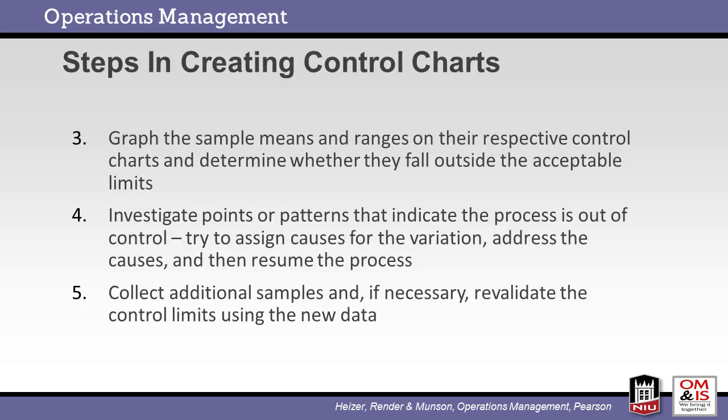Next, we create the control charts from the previous data. Using the control charts, plot the actual measurements over time. Action plans would be created to resolve any issues identified by the process limits. Once complete, process data is gathered and plotted to confirm the impact of the improvement. The process limits may then be readjusted if appropriate.